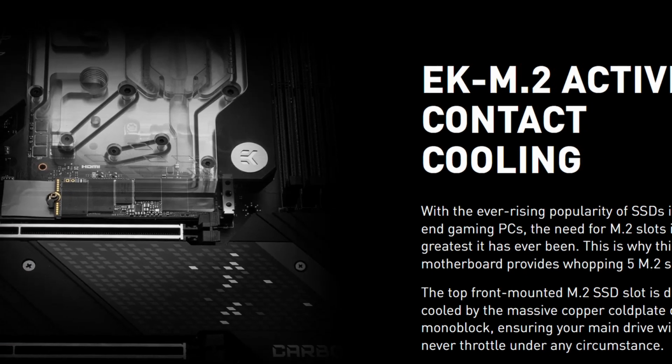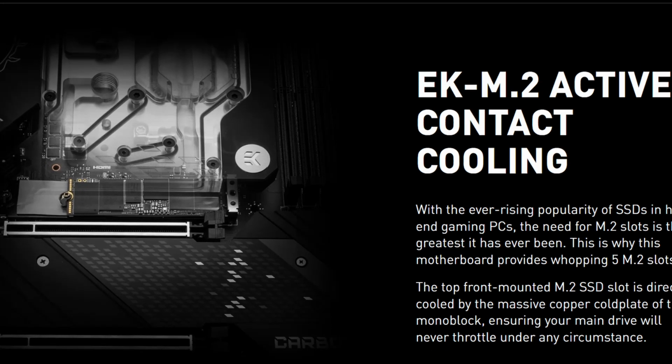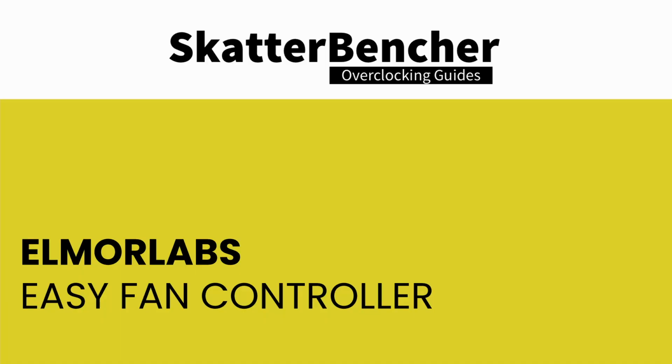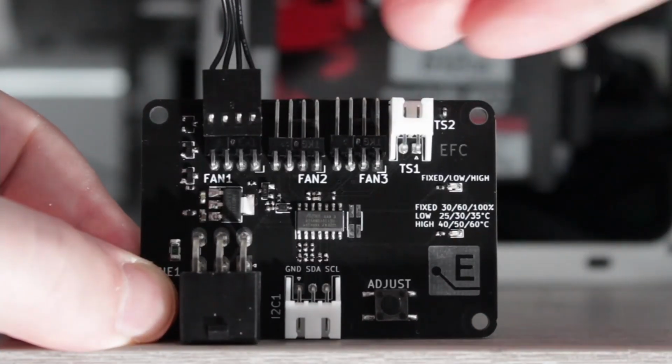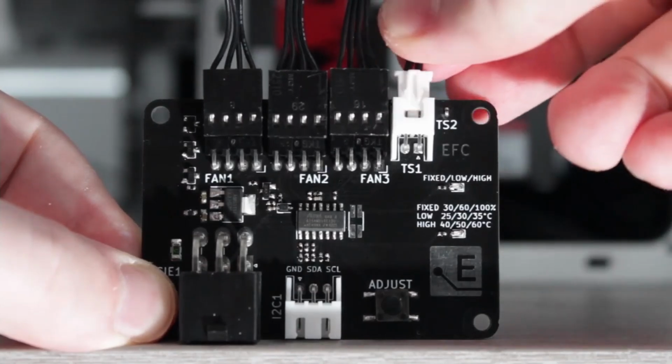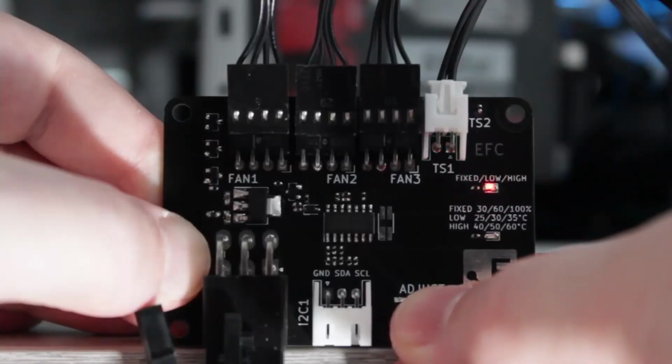We place the WD Black SN850 SSD in the top M.2 slot, which is cooled by the EK monoblock. We use it exclusively to measure the M.2 drive temperature during our stability testing. I covered the Elmor Labs EFC in a separate video on this channel. Without going into too many details, I've attached an external temperature sensor from the water in the loop to the EFC. Then I use the low-high setting to map the fan curve from 25 to 40 degrees water temperature. This is used for all overclocking strategies.